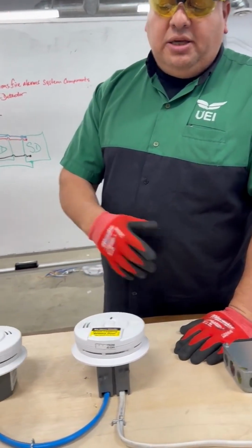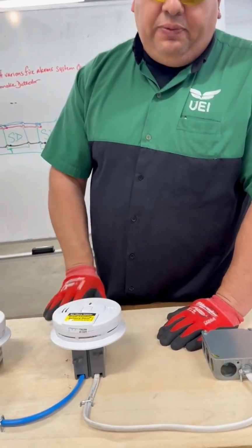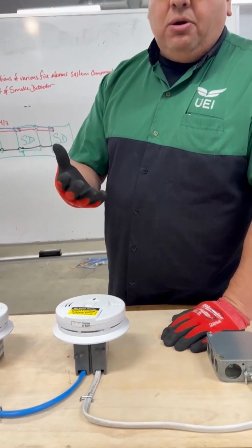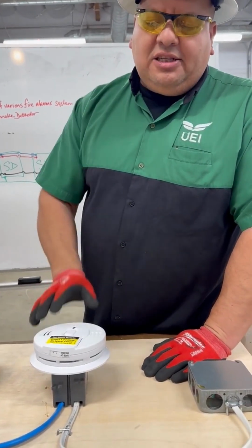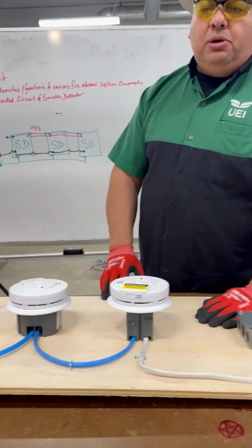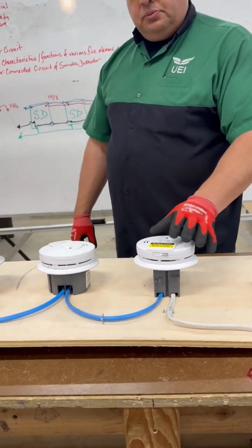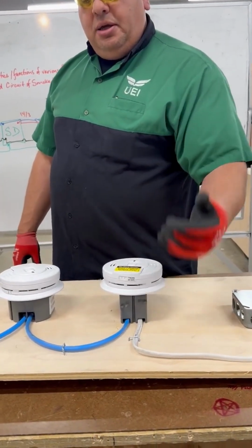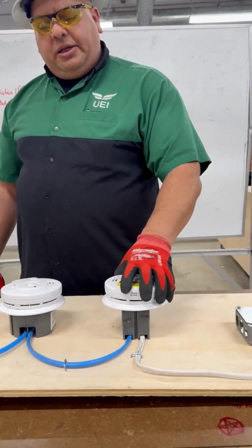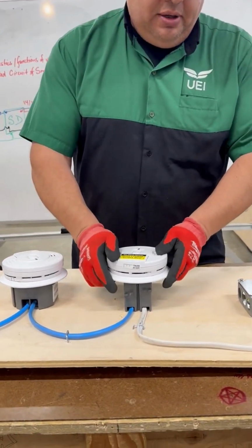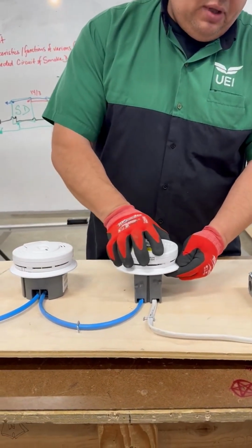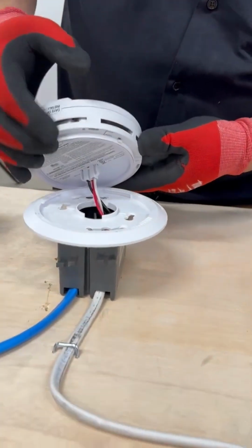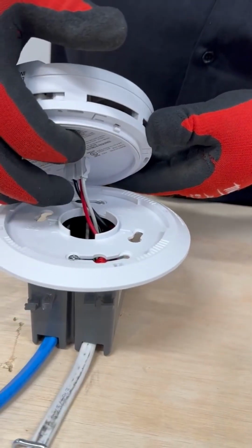Therefore, the detectors are not going to operate on an optimal level. So the simple test is if the outside surface of the smoke detector is impacted by that grease or dirty air quality, then that's a sign that the smoke detector should be replaced, even though the battery might be in good working order. So all we're doing is bringing that ungrounded, grounded neutral, the grounding, and putting it into the interconnected plug-in circuit that is provided from the manufacturer. We got that plug-in cap with the power leads coming in.